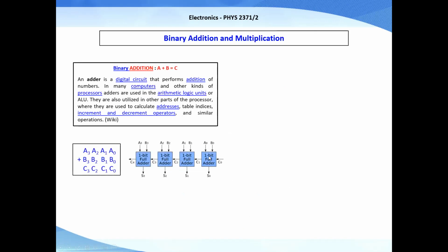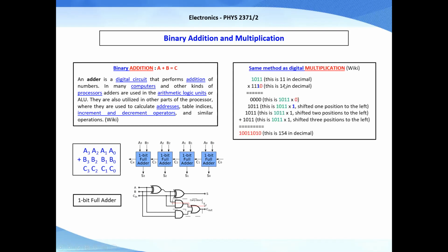I showed how you use a full bit adder that works on each set of least significant bits here, A and B of a number. A is a number, B is a number, and it gives out S, an answer, and a carry. Each one of these adders does that: 2 bits in, a carry in, a sum out, and a carry out.